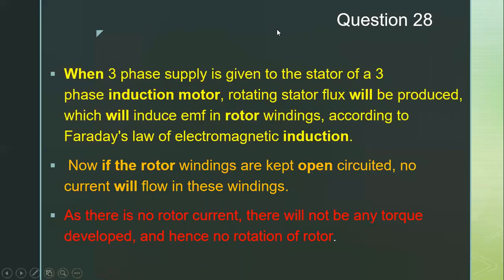When the three-phase supply is given to the stator of a three-phase induction motor, a rotating stator flux is produced, which induces an EMF in the rotor winding according to Faraday's law of electromagnetic induction. You know that when the three-phase supply is given, an EMF is induced in the rotor winding.